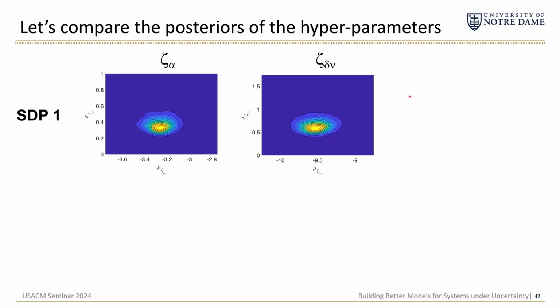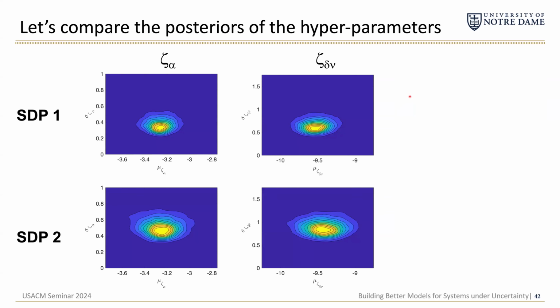Then if we look also at our post-yield stiffness ratio alpha, or at delta nu, which I highlighted earlier as perhaps the degradation parameter that contributes the most, it has a value that is non-zero. We can compare this for steel damper pair 1 to 2 again.